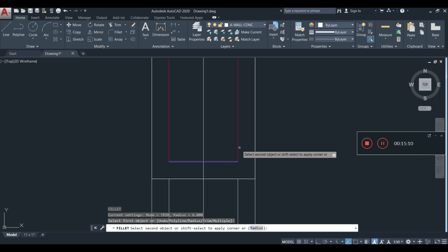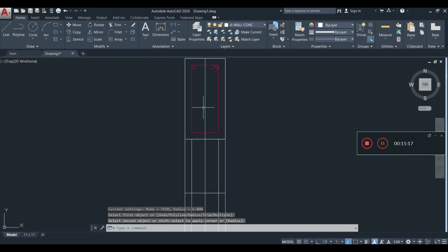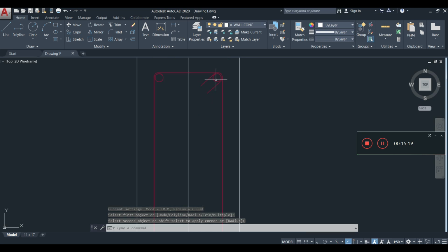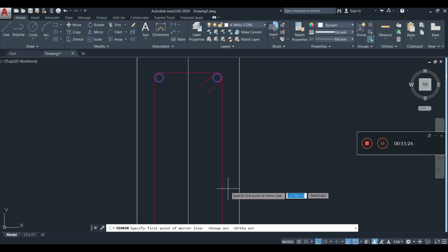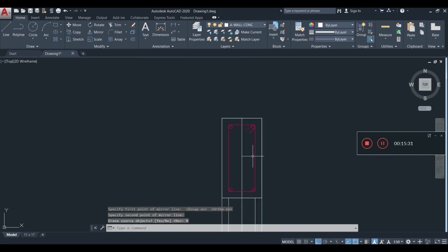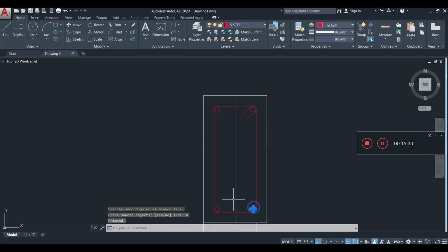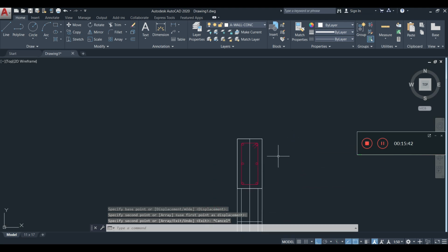So this is going to run me up some time. Now if this was a sketch and I'm doing it on paper, I'll probably be finished by now. So let's go ahead and mirror these circles down. Turn on O snap for that. Find the center. Then I also need to put two of them in the center as well. Yeah, I'm just eyeballing it right there. So this is our belt beam.